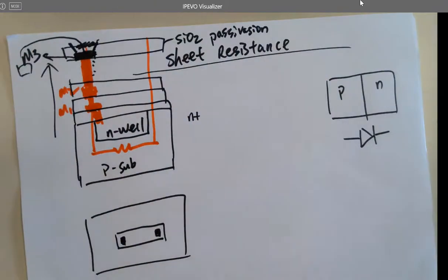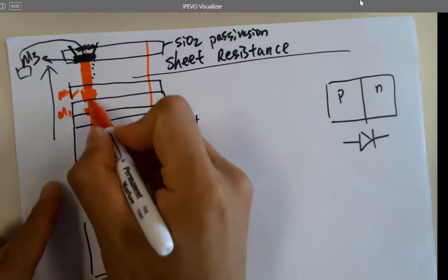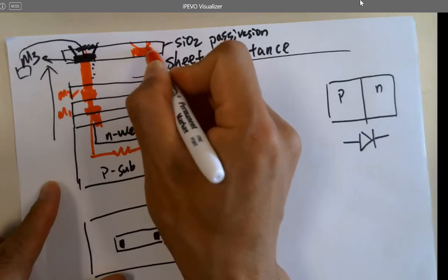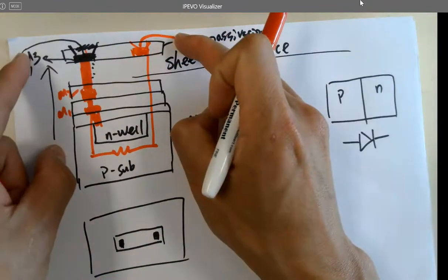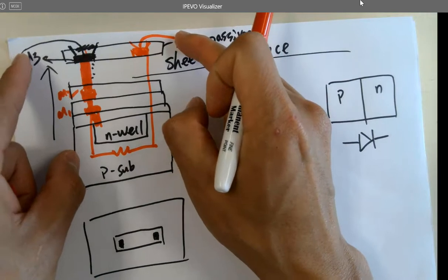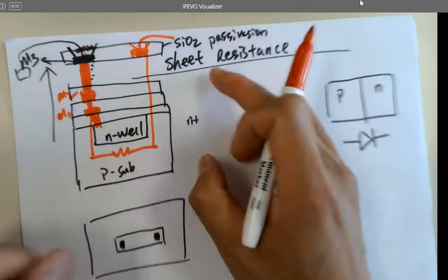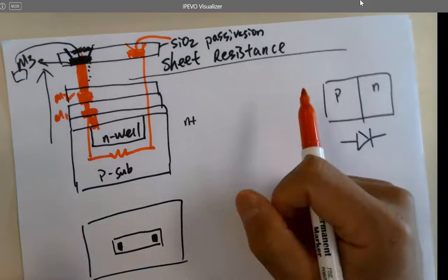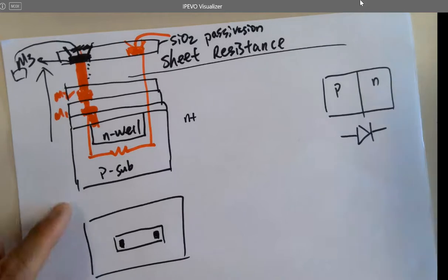If you do the layout as you did yesterday, you lay out an N well and do nothing about it, just a chip with one N well in there, like 1 k ohm. Then you have all the vias going up until metal 3, and you wire bond it in the lab. You put the multimeter here, and you get 1 k ohms. So you build a resistor in the chip. It's a nonsense chip, but just a resistor in there. I can tell people, don't use a surface mount, I got an even smaller resistor for you. It costs you $6,000 just to make a little resistor in there.